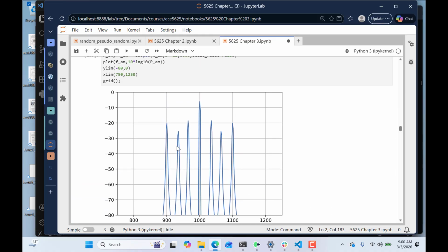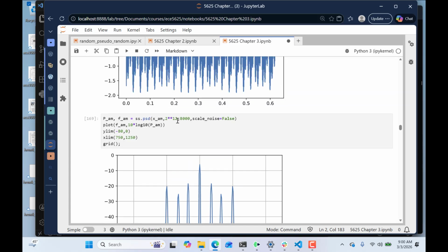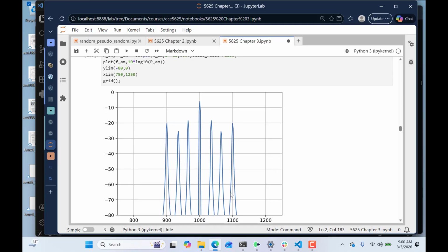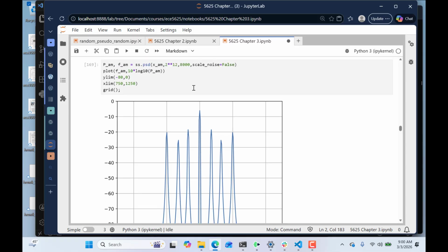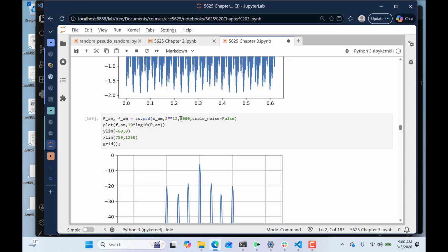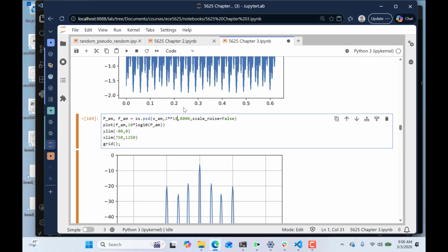And then if I'm not happy with the sharpness of this, it just says I'm not using enough FFT points because I'm getting kind of not really razor sharp peaks. So I could increase the spectral resolution if I wanted to. And to do that, I could go up here and I could just say, okay, I'm going to take this up to maybe 14.